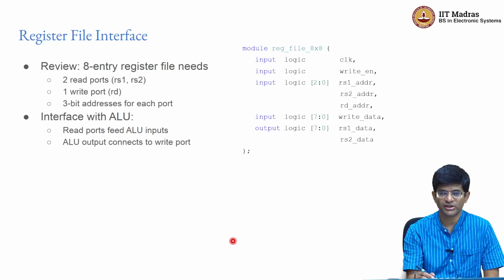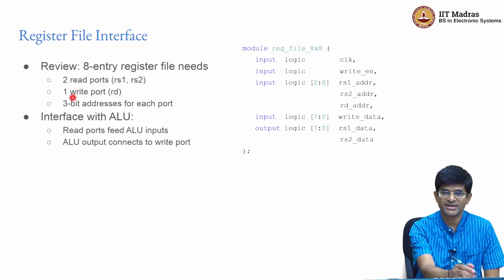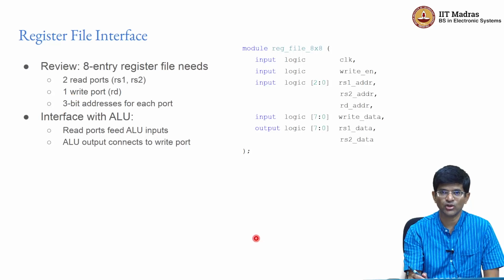The example that I showed for the register bank had only 4 registers. But if you think about it, I already have A, B and C as my 3 input parameters. I have the number 4 which I will probably need for some computation and needs to be stored somewhere. I then need temp1, temp2, temp3 and result, right. So it looks as though trying to get everything done with just 4 registers may be possible, but it's not going to be easy, right. So let's not skimp on registers here, let's just go for 8 registers in this case. What that means is each register address is now 3 bits because I need to select a value between 0 to 7.